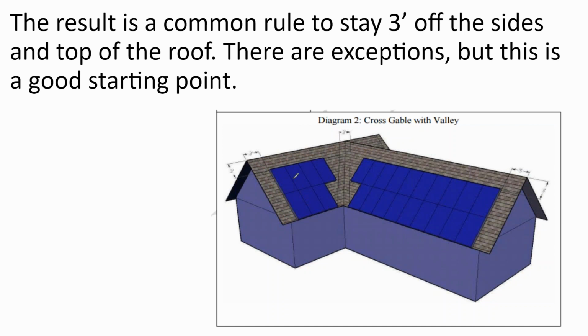And furthermore, 3 feet is not as big as 4 feet. I feel much more comfortable on a rooftop where there's 4 feet instead of 3 feet. And on top of that, some rooftops you can get some overhang from the structural wall, and you really want that first attachment point, assuming that it's going into the structure. So there's more than one reason to even be more conservative with this.